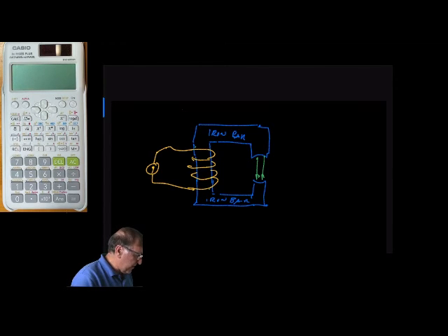If we increase the current or turns, either one would increase the magnetomotive force at the gap. There is a limit, however, when all the magnetic domains line up. This is called saturation, and we'll explore this more when we talk about motors.